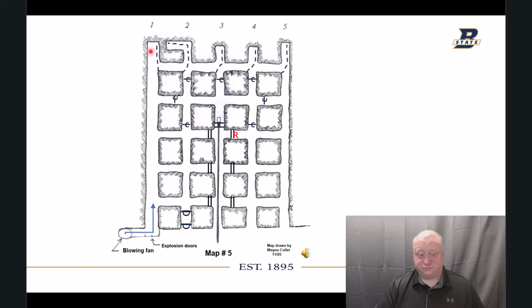Shuttle cars are changing out at this line, not up in here. So we'd be mining over here, fresh air coming across the miner, then coming back out the back side of the curtain and coming around every single one of these faces, because they're all advanced up, nothing's connected through, and coming back out the return.